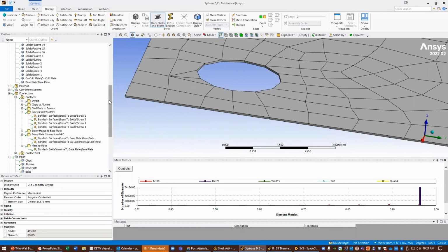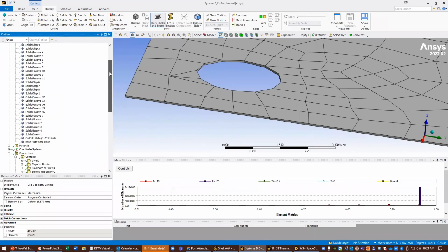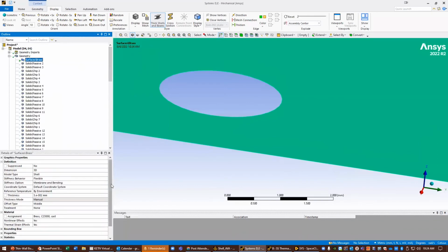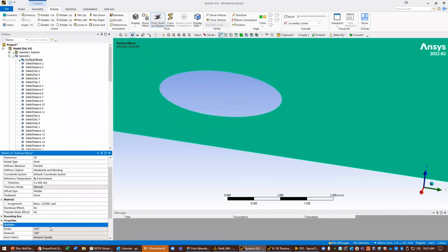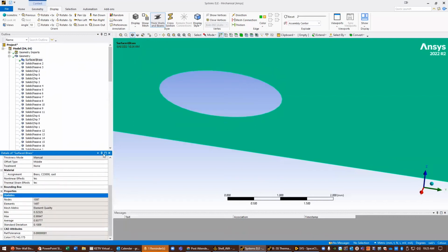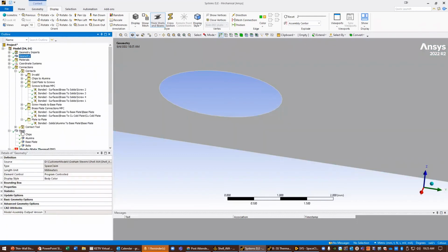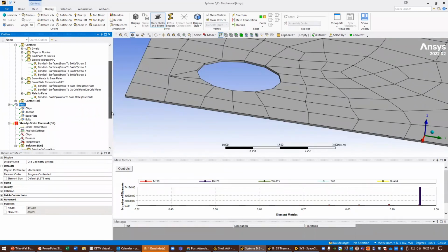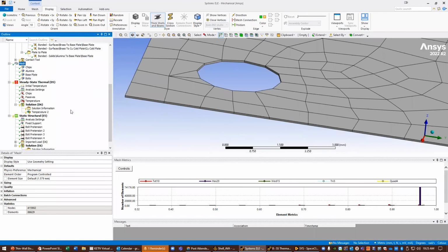That means I don't have to mesh all that extra mesh. It's much cleaner and faster to run this model. So the total mesh statistics for this body now are in the 1500 realm, whereas before it was in the 5 million realm. And now the total mesh for the entire model is only 400,000 nodes, or 86,000 elements. And so the model runs much faster.